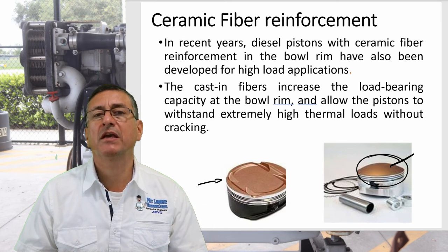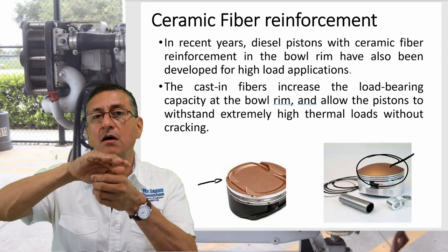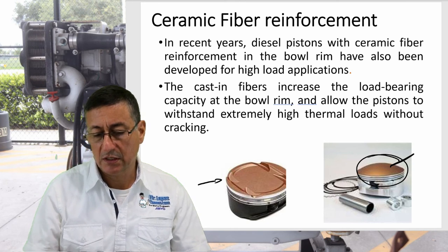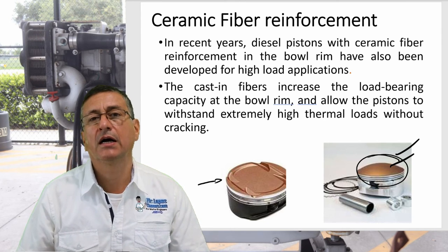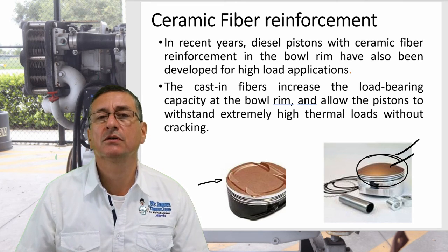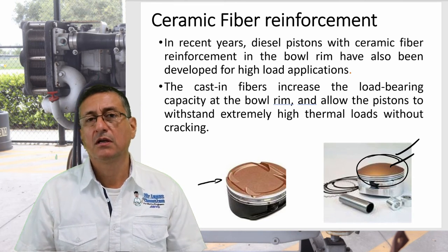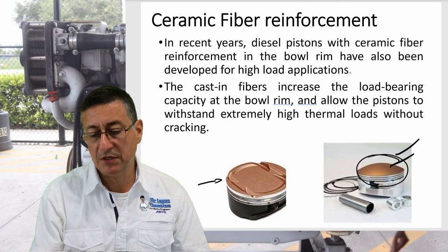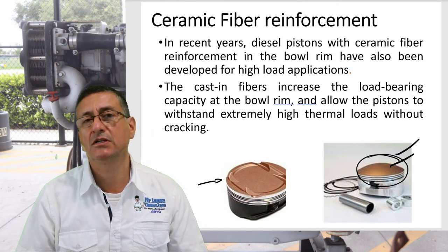They add ceramic materials on the dome, on the head of the piston, creating a dome like this one that you have here in the picture. But this is not recommended in diesel engines because remember, the diesel engines work at higher temperatures. What happens if that piece of ceramic is fractured, is cracked?